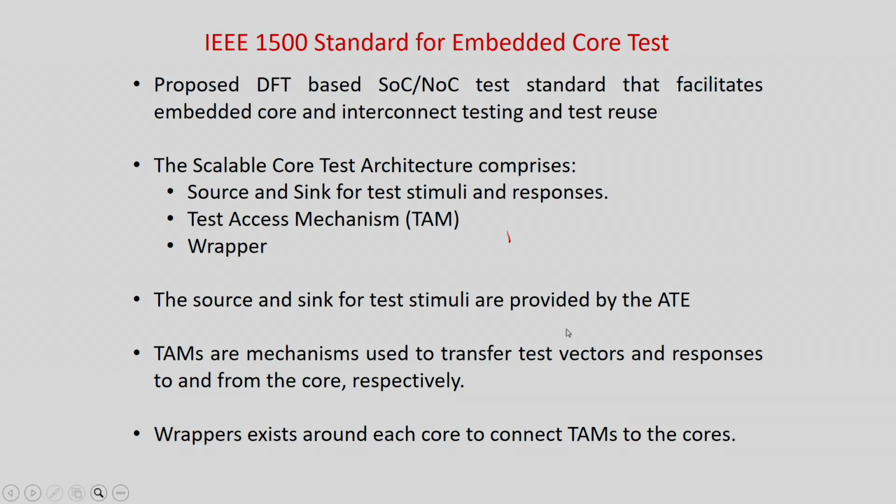So this standard, as I told you, is the core idea of core-based testing, and there were different levels of standards that came into the picture. We started with 1149.1, then 1149.4 which is for analog, and for embedded core test they call it the IEEE 1500 standard. It is a proposed DFT-based NoC test standard that facilitates embedded core and interconnect testing and test reuse.